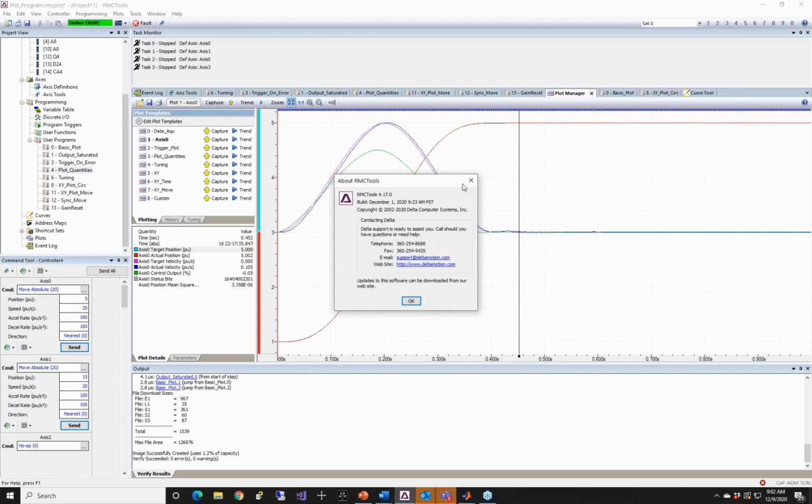Other times, maybe it doesn't matter so much, because if you get off of your target position from any one of those axes, you may have a following error set up that says, I need to be within a 1/10 of an inch, or things are going to stop, and I'll make sure that both my axes stop. So sometimes that following error is okay.